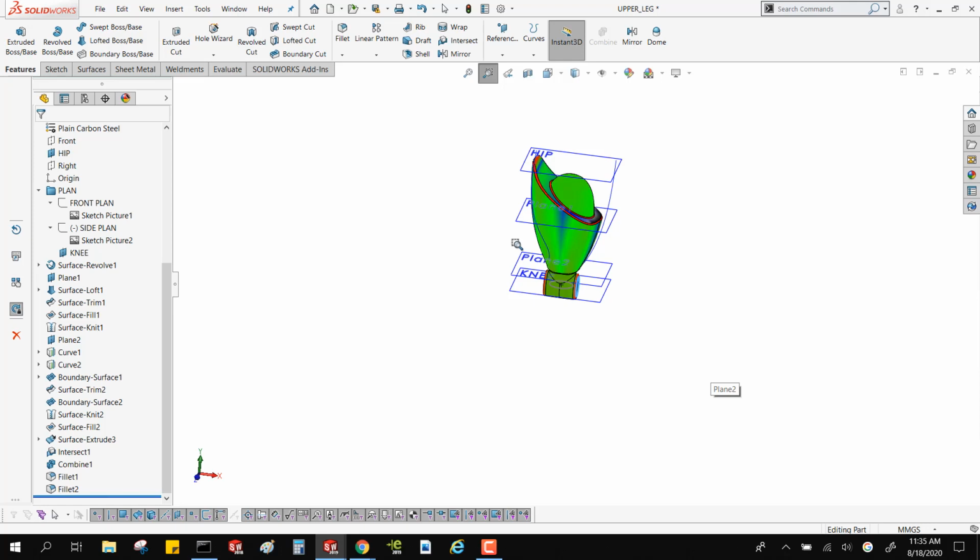Yes, sir, I had a question. That last G3 trick you were showing, it looked like in the sketch that curve wasn't fully constrained, yet it looks like everything stayed curvature continuous. I was just wondering if you had a comment on that. I think the curves were still blue, if I remember, in that sketch. Yeah, the curve was still blue.